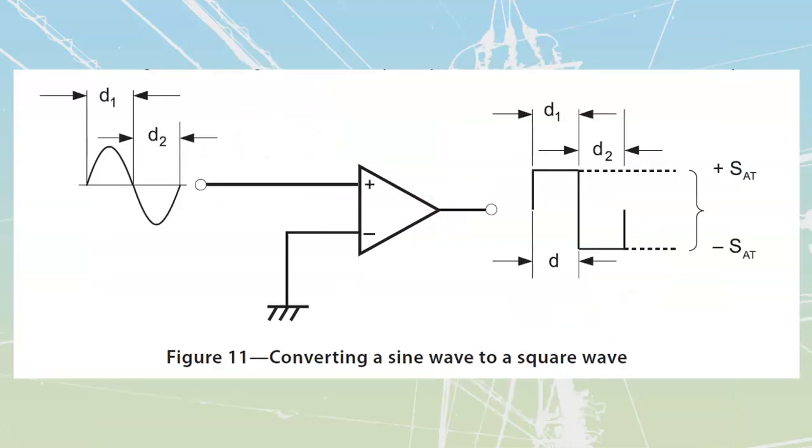Last one that we're going to talk about for this is using an op-amp to square a sine wave. This is a lovely thing because these things drive so incredibly rapidly into full saturation. What we are going to do is, almost the exact second that we cross over top of this axis over here, it is going to see that it's a bit more positive than this. This is at my 0 volts, which is the same as my neutral. Remember, we ground the neutral there as well. So we're going to have that at 0 volts.